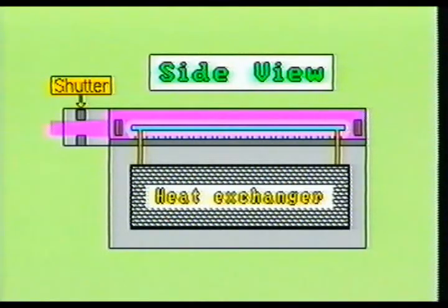Since the CO2 gas laser operates in a continuous mode, it will almost always contain a shutter device which is used to control the output of the laser beam. The shutter is water-cooled and is electrically opened when the beam is required. When the beam is not required, the shutter will remain closed and the energy from the beam will be dissipated in the form of heat on the shutter device.